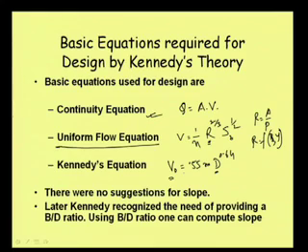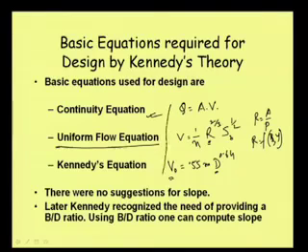But in this entire computational process for designing the channel, there is no mention of the slope. That means if we calculate the size of the canal, we are not considering the bed slope, particularly when we are using Kennedy's equation. We find V0 if we assume a depth d, and then we calculate the critical velocity. Then once we get the critical velocity, we can get the area of the canal.